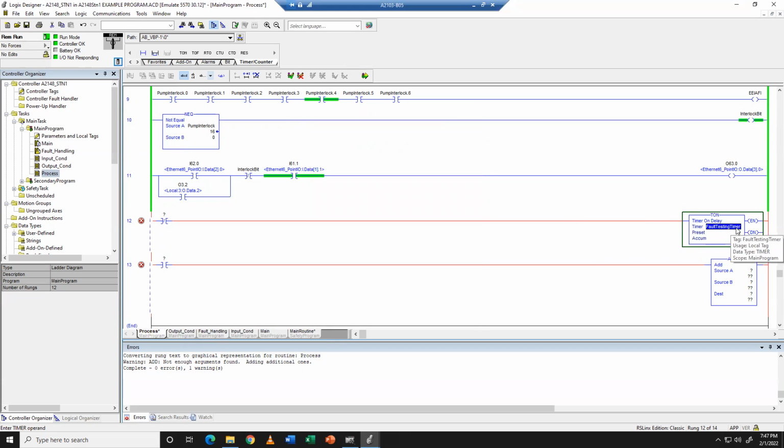But I know Addie asked this question earlier about tagging. If you want to use the tag in an HMI and you want it to be the same from wire tag, from conductor, into the program and then into the HMI, one thing to consider would be character limits inside your HMI software.